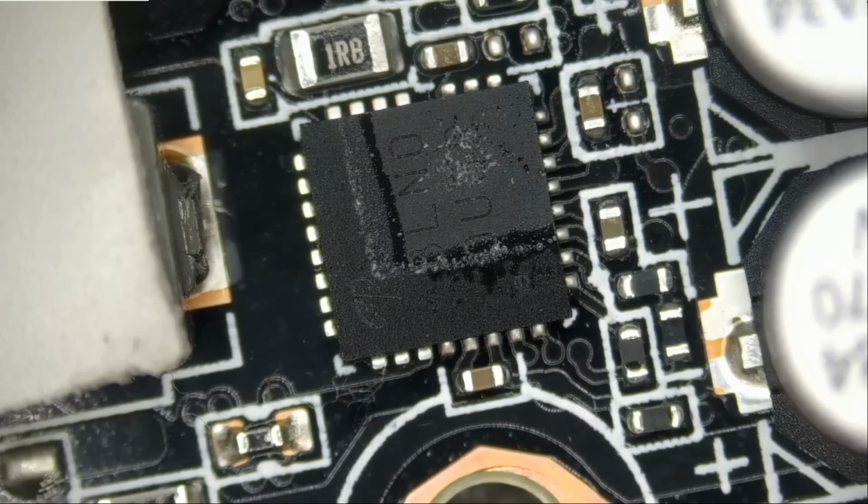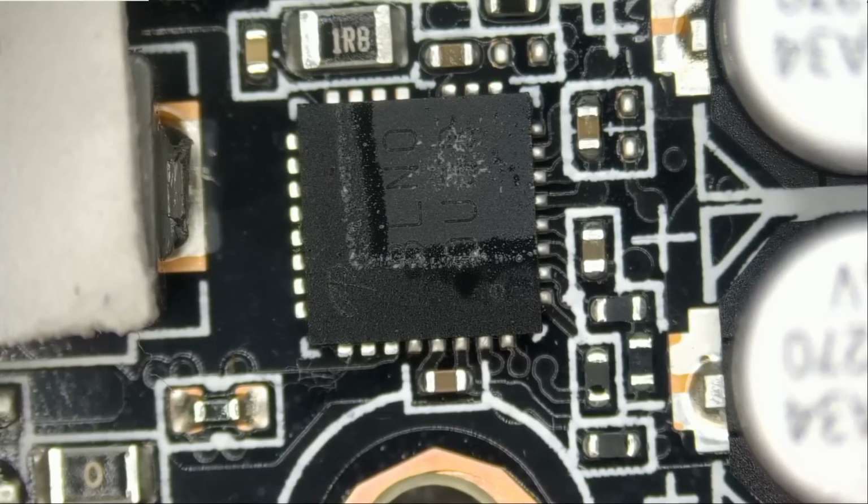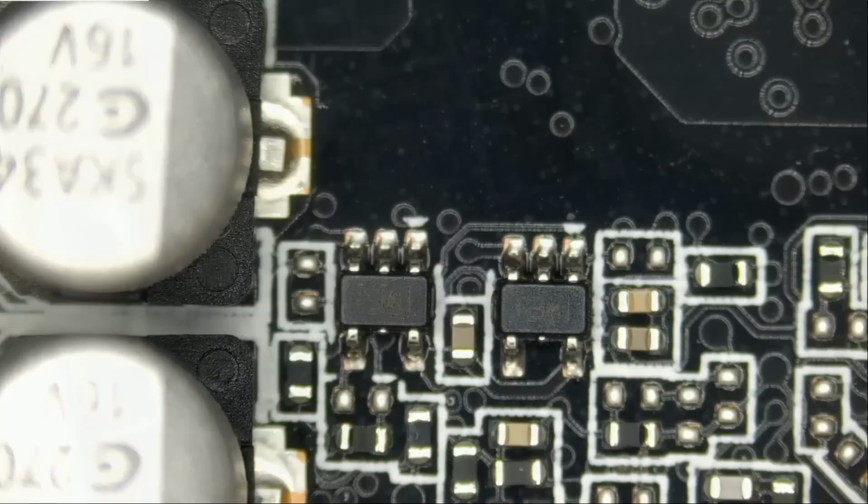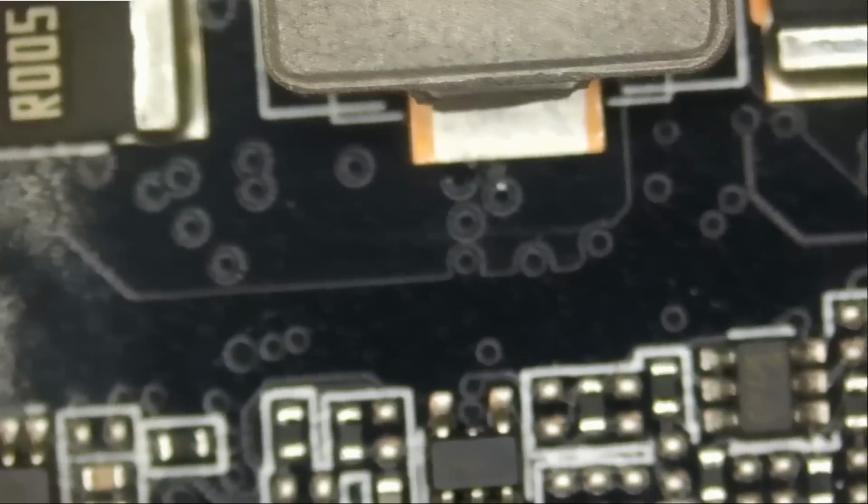Let me pause. So what we're going to do now is inject voltage at the short, at the coil, and we're going to monitor the board under a thermal camera and see if anything stands out as being hot, specifically the V-core MOSFETs. We did this a million times on the channel, measuring for a short using a thermal camera. So let's make it 1,000,001.